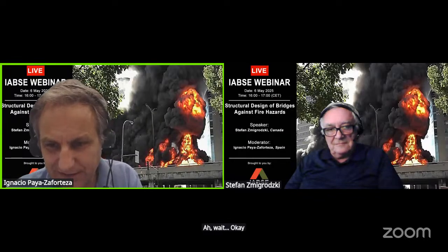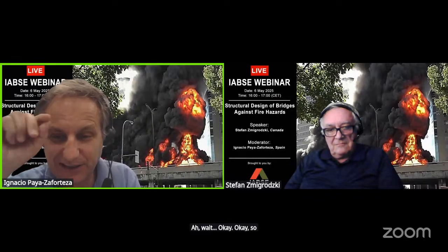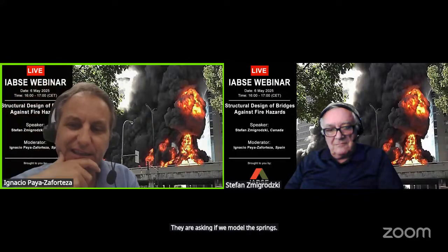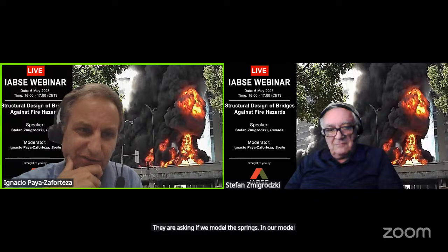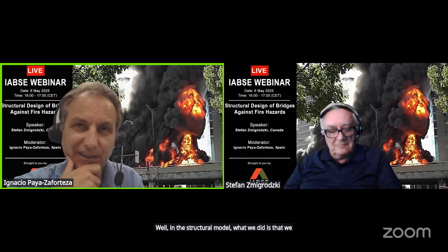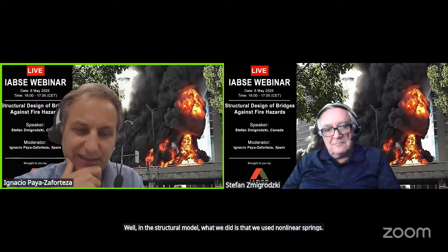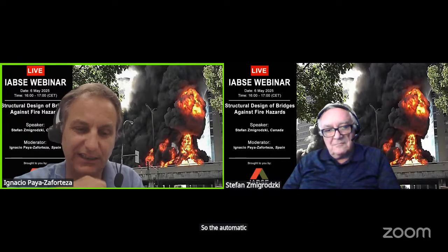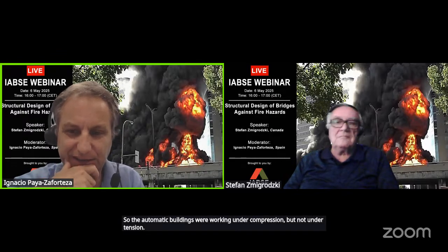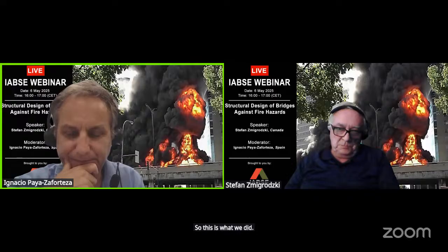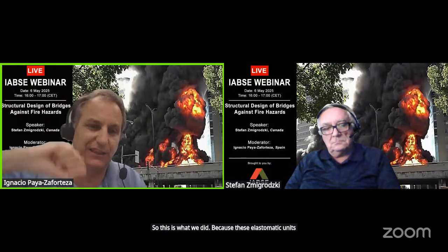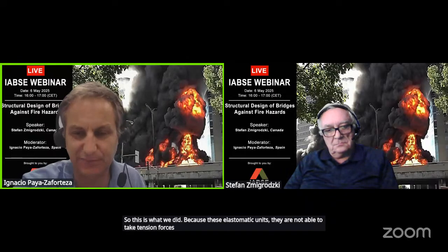Okay, so I have one question. I will reply. They are asking if we model the springs in our structural model. Well, in the structural model, what we did is that we use non-linear springs. So the elastomeric bearings were working under compression, but not under tension. So this is what we did. Because these elastomeric bearings are not able to take tension forces. They can only take compression forces.